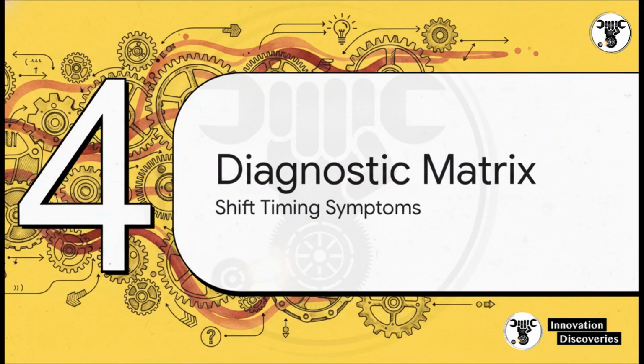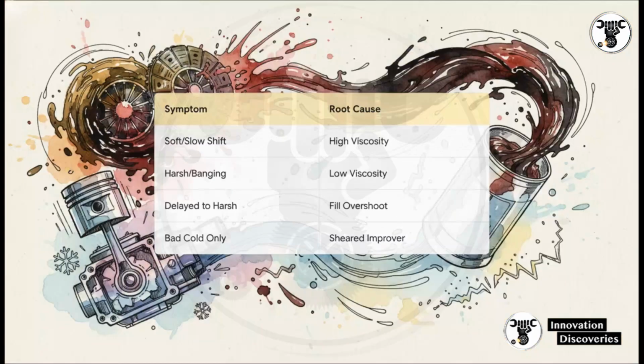Let's transition over to Section 4, Diagnosing Shift Timing Symptoms. We've got a really handy diagnostic matrix for you. And this brilliantly illustrates what you should be looking for. Try using this matrix on your next test drive. If the shift is soft or slow, the root cause is likely high viscosity. If it's harsh or banging, you're looking at low viscosity or shear degraded fluid.